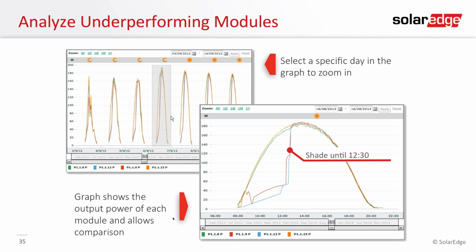In looking at this, you can quickly determine what kind of maintenance you want to do. Maybe this was expected shade, and this is acceptable performance, or if this was unexpected shade, and you need to work something out with the customer. This will provide you some insight, and then you guys can make decisions on what are the appropriate actions to take in order to resolve the situation.